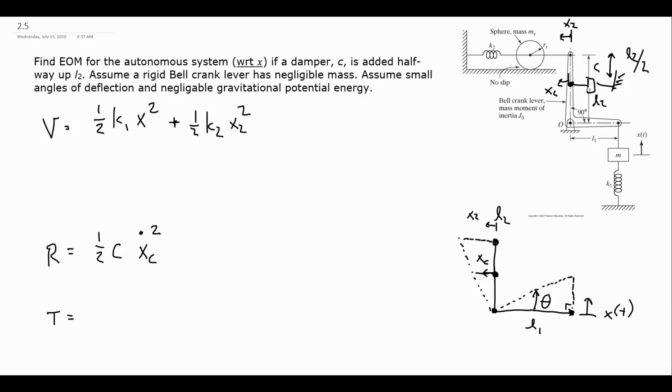Let's see, what's the kinetic energy of just the mass m in the system? It's translational, so it's 1/2 mv squared. So 1/2, the mass is just called m, and its position from its equilibrium point is x, so its velocity is x dot, and that gets squared. And that's it. That's the translational kinetic energy. That's all that mass has.